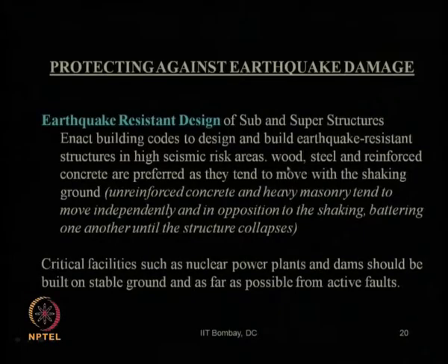You should go for wooden buildings, steel structures or reinforced concrete structures, which are preferred, as they can take more movement during shaking. But of course, you need to design these structures, whether RCC, steel or wood, properly to take care of all the clauses of design codes and the issues involved with superstructure and underground structures during the earthquake resistant design and construction process.